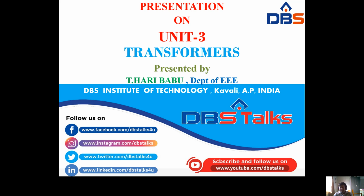Suppose the circuit is referred to the primary: the primary parameters R1, X1 are placed the same in the primary winding. Now the secondary parameters R2, X2 must be transferred from the secondary side to the primary side, by multiplying with the transformation ratio.